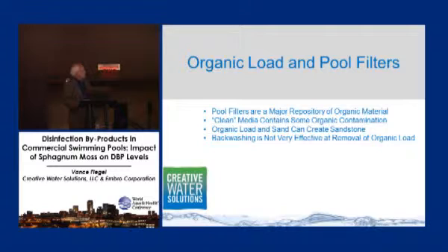Again, in our laboratory, and I'm not going to go into this today, we've done a lot of work looking at sand filters and the material contained upon them. One of the things we've done is look at the effectiveness of backwashing in removing the organic load, and we found that backwashing alone is not very effective. In fact, it only removes 30 to 50% of the organic material on a sand filter. Even if you backwash numerous times, that seems to maximize at about 50%. So even when you backwash efficiently, you're still not removing the majority of the organic material from the sand media.